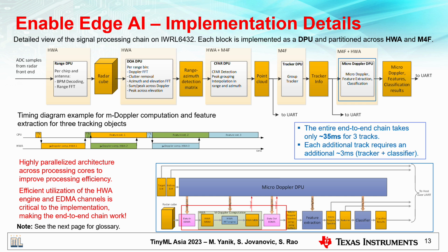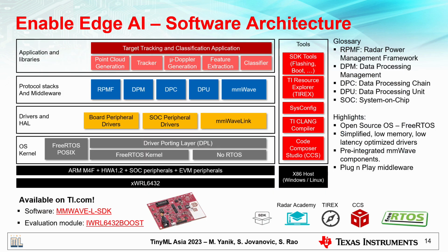So now the device EVM is available on ti.com, and we also packed everything in our latest SDK framework. If you check out this SDK, you will see everything needed to make this device run: all the low-level drivers, RTOS, and data processing units for each block, already available with all the source code, and the whole demo application, which runs all these processing blocks to produce the final classification, also available in the latest SDK release.